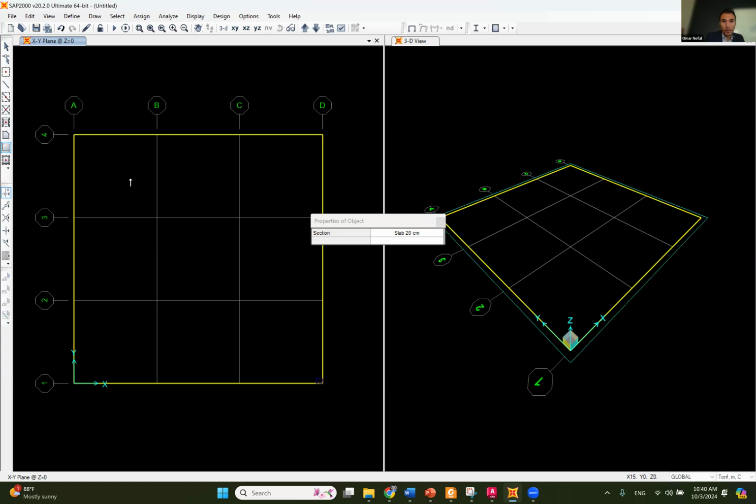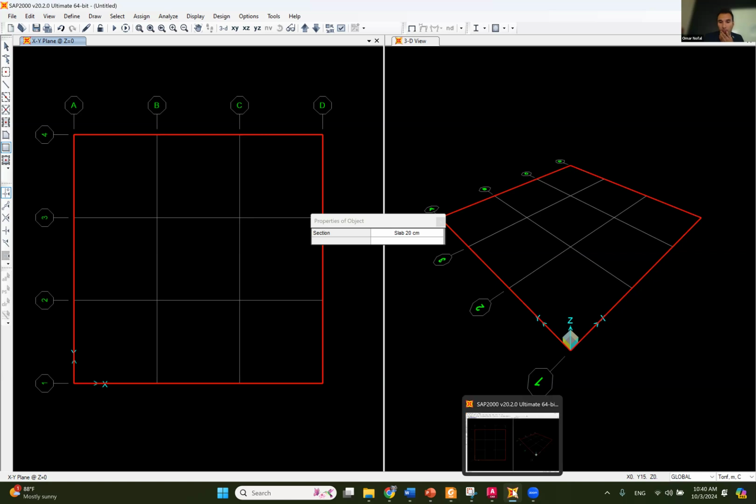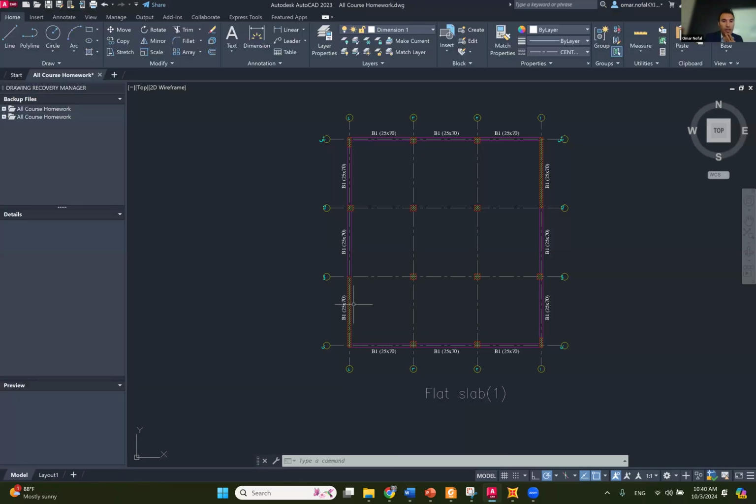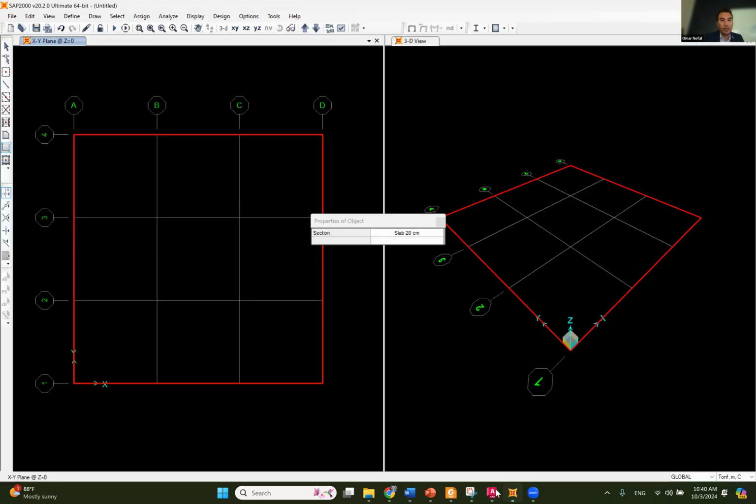All right, and then I'm gonna make one big slab like this. The problem with this one is that I have hinges, I mean columns, in the middle, and I want to model these columns. I'm gonna neglect this shear wall; I'm gonna make it next time. I'm gonna assume that there's a column here and a column there. So I want columns all over the place here. To do this, I need joints in the middle, and I don't have joints.